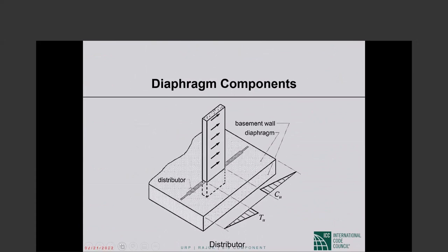Now, when a shear wall, or this could be a whole tower, sits on a podium, which is very, very common. Okay, a tower, but then very low levels. We have a much bigger structure. So the base shear from the tower or the shear wall will ultimately be resisted by those basement walls. But how do you go from here to there? And this is like the collector.